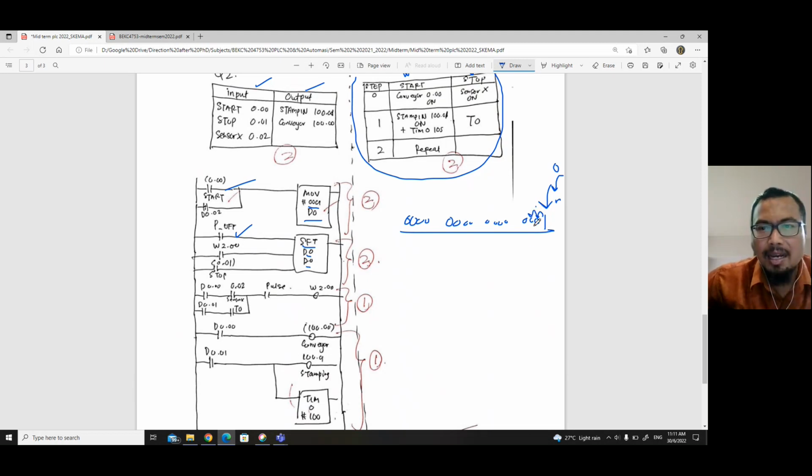So at any time we have only one location that has 1, which means this 1 will turn on the process. So this is the shift register method, where you turn on the process by using the bit. At any time only one bit is 1 at a certain location, and the rest of the bits will be 0.